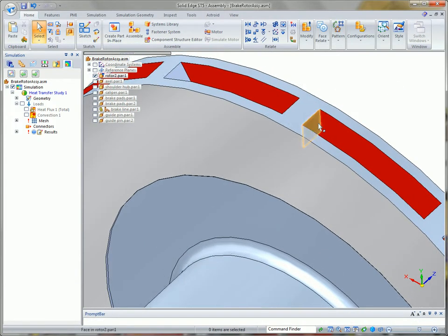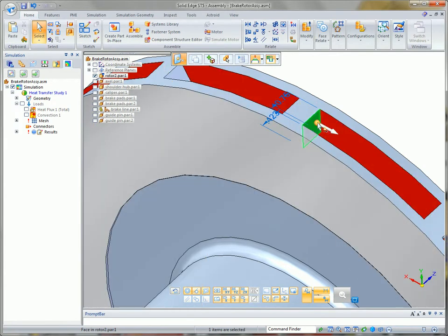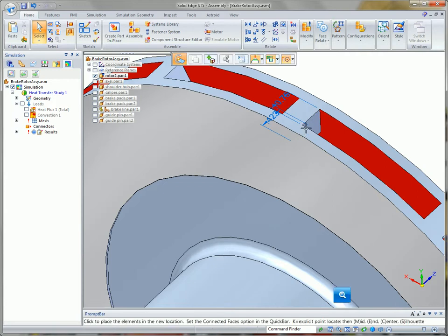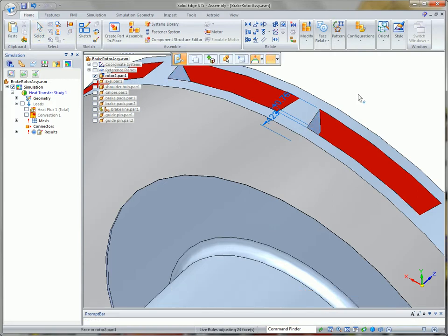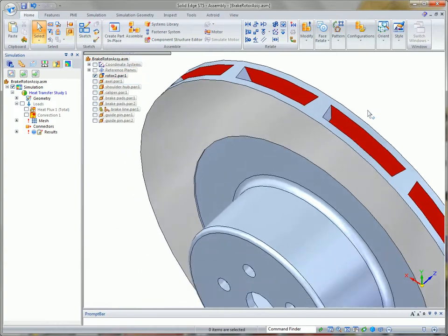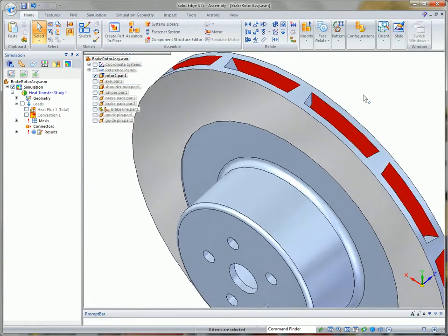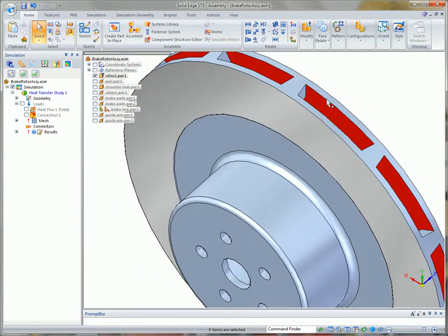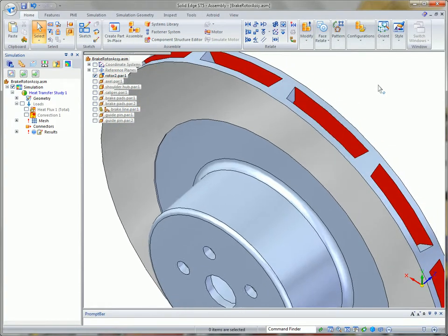If I want to add strength or change the design in any way, we use a tool we call steering wheel, in which you can see I can identify, in this case, the outside ring on the steering wheel, and I can add an angle to that particular rib. When that's complete, because I've removed some of the material from the rib, I might want to thicken these two plates just a little bit.